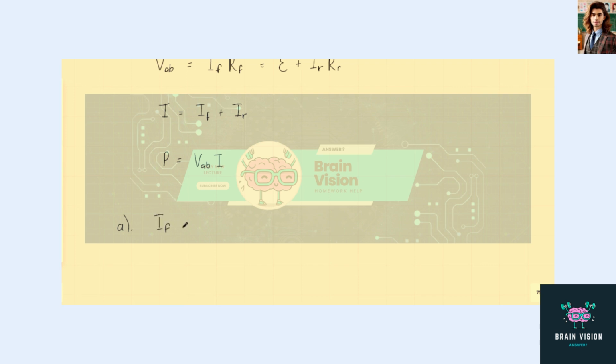So we know IF is equal to VAB over RF. So that's 120 volts divided by the field resistance, the field coil resistance of 218 ohms. This gives us the field current to be 0.55 amperes.